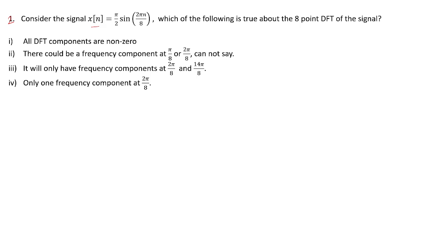So for that maybe you want to do some brute force DFT computation and check the different frequency components individually. But you can do it by brute force, though it is not simple. Brute force is good when you have like a 2 or 4 point DFT. If you move towards higher points, then brute force is not very helpful because your computation becomes really expensive.